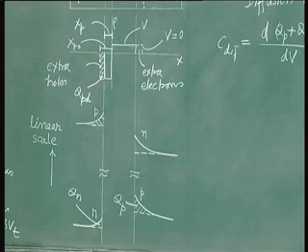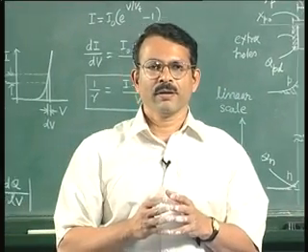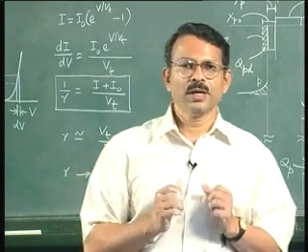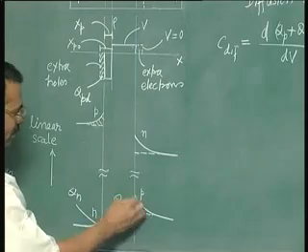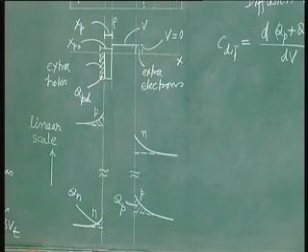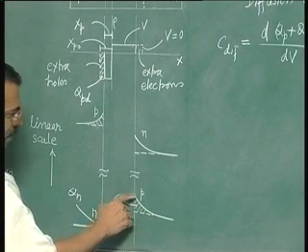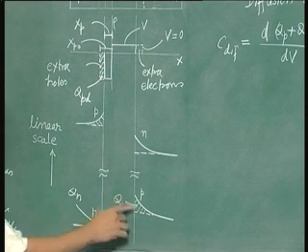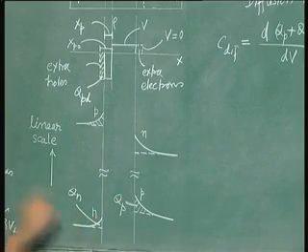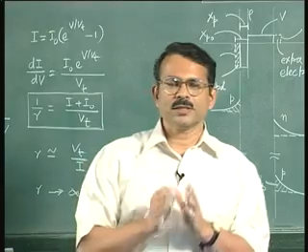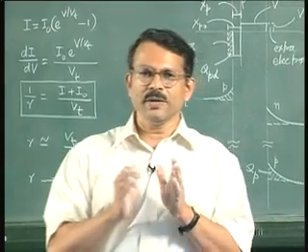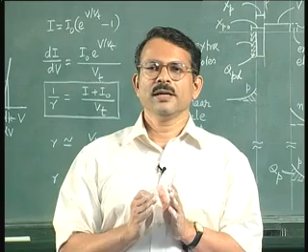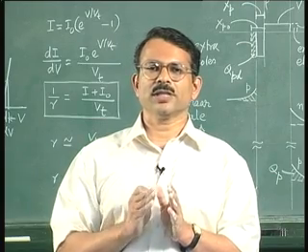Now this is where you must understand the quasi-static approach. Why is the word quasi-static being used? Because please note that these distributions which I have drawn here are known for the static or steady state conditions. They are exponential, and therefore the area can be easily determined once you know the distribution. Now in steady state conditions the distribution is exponential because you take the continuity equation for the minority carriers and then you set the rate of change of the minority carrier concentration as 0.